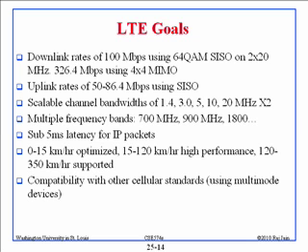Multiple frequency bands. Whatever band you get, 700, 900, 1800, just like WiMAX. Sub 5 millisecond latency for IP packet. Now, this is a distinguishing factor. Why distinguishing? Because one of the reasons they asked us, why do you need LTE? Why not just WiMAX? They said WiMAX is not fast enough in latency, and the reason it is not fast enough in latency, suppose you get a packet. You have to tell the base station that I got a packet. That will take how long?